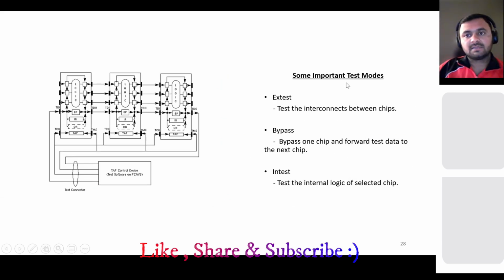Then there are some important test modes. It has around, I think, 10 different test modes, but basically these 3 we use extensively: EXTEST, bypass, and INTEST. Bypass I already told. Suppose in a chip you have these 3 blocks and you want to test only the middle one, or you want to test the third one, so you have to bypass. You use this bypass register, put the bypass instruction, and it will bypass these 2, and it will test the third. Or you want to test only the second, so you bypass first and third, and you test the second.